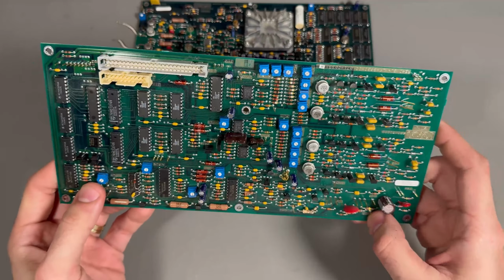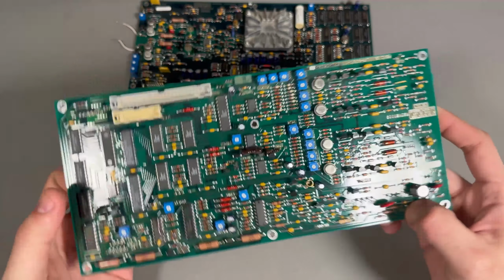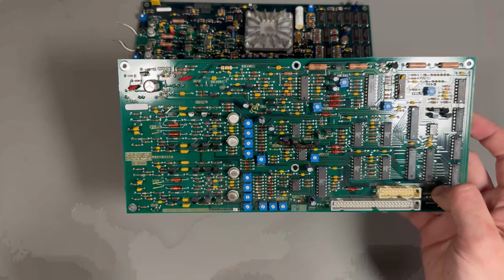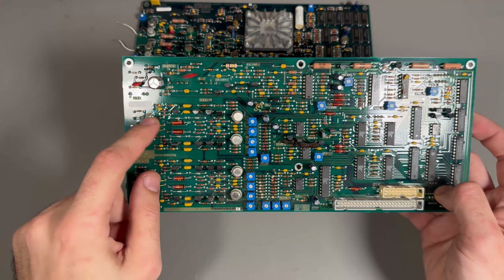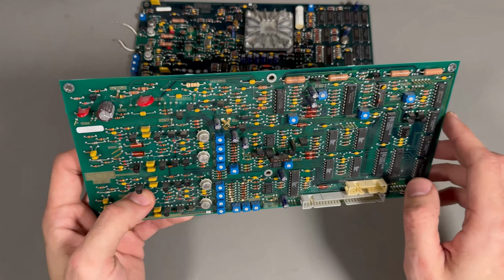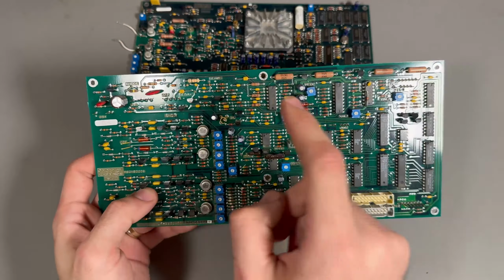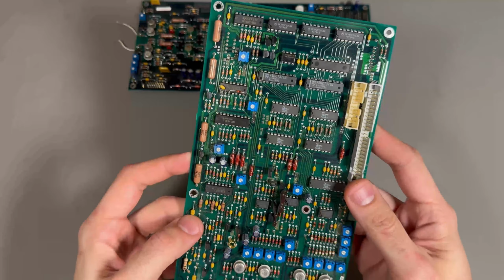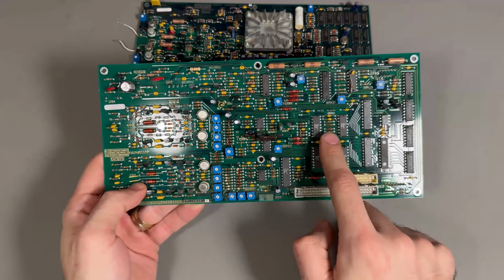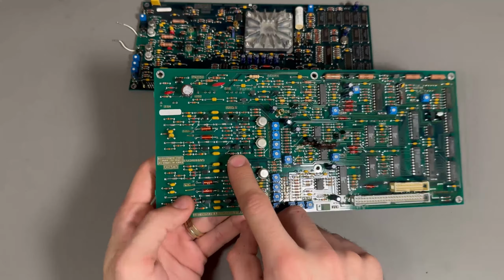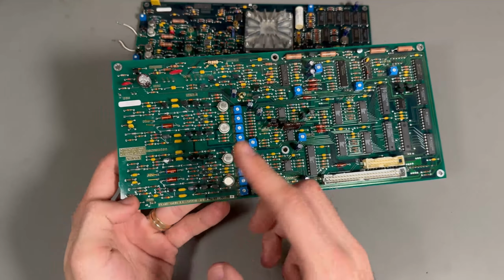This is for the read gun, I think. Read gun assembly, yeah. So this is all the video amplifiers for the... this bit here is the scan control, so the output amplifiers for the scan. You can see these are the terminals that went to the scanning. These are DACs, which I'm assuming are generating the raster pattern for the scan. And there's some other stuff here which is related to biasing the tube, the read gun basically. These are DAC08s, by the way. So my assumption is that these are generating the rasters for the X and Y scan, and these amplifiers and circuits around here, along with these transistors, generate the deflection currents for the scanning yoke.